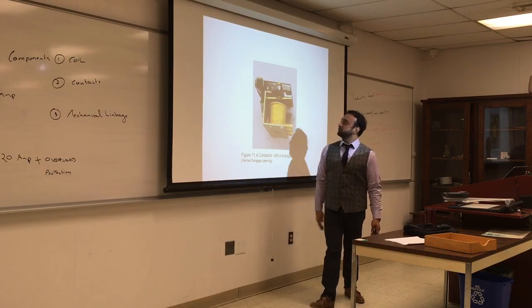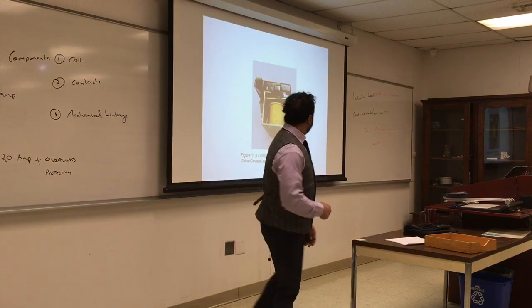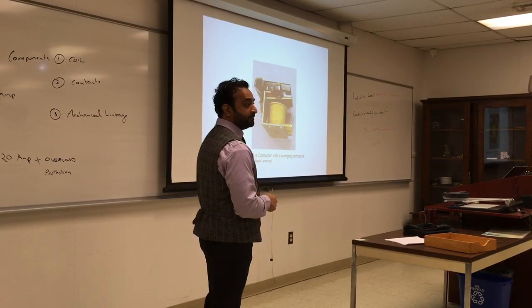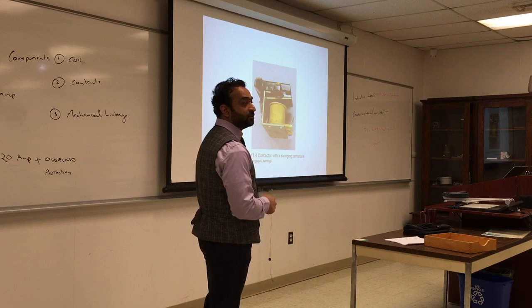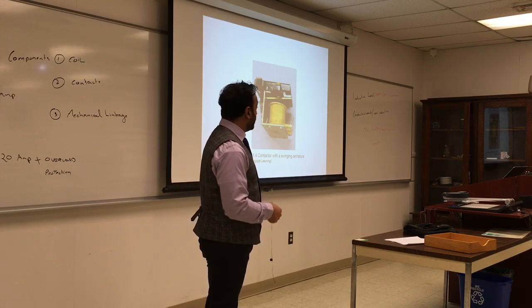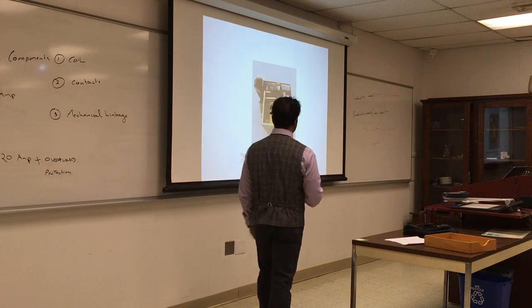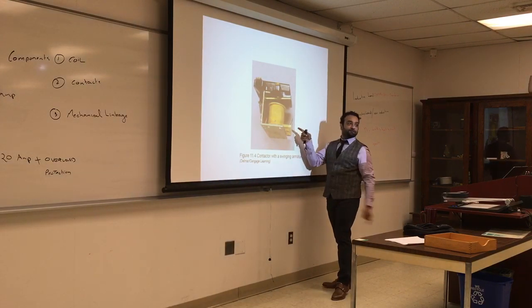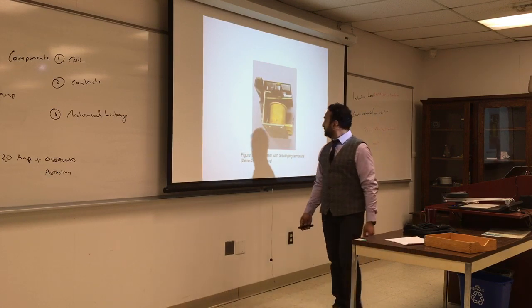So again, what would you expect to be the problem here? Either the spring will be broken, the contact here will be dirty, or something stuck in it, usually insects or moth. They get stuck in the middle, or ants, or whatever, or a leaf, or they just rusted. Or the coil is bad. The coil testing is very easy. You'll go with your ohmmeter and test the resistance of this coil.